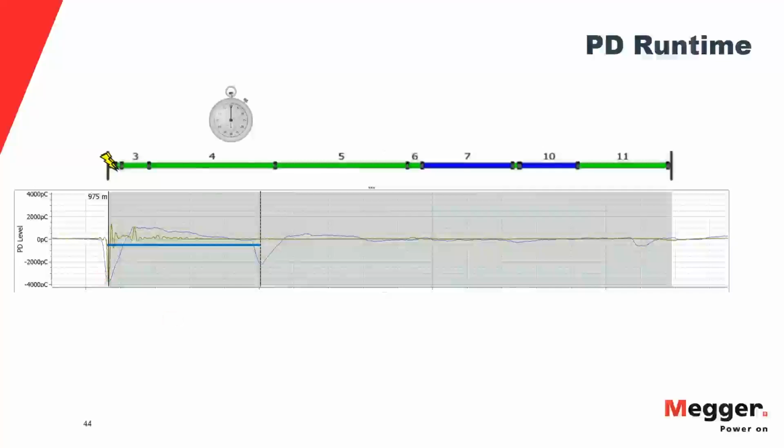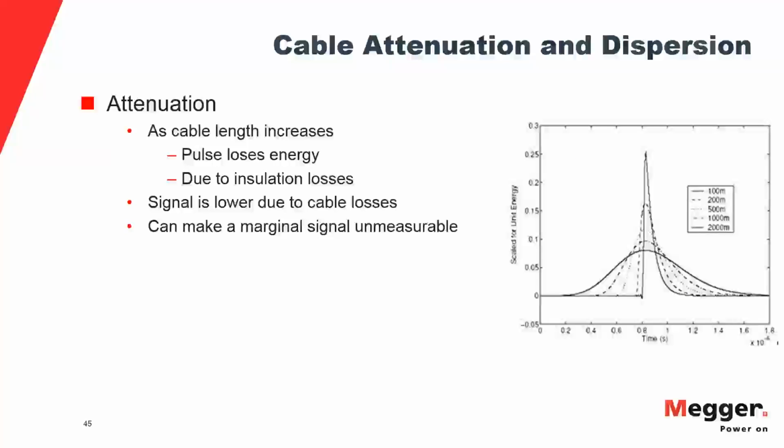Of course, Megger has the testing equipment for everything that we've talked about today. So we have here our VLF Sine 45 and also our 62. So we can now do VLF sinusoidal testing up to 45 or 62 kV. And these are suitable for PD or tan delta diagnostics with sinusoidal waves or VLF withstand testing.